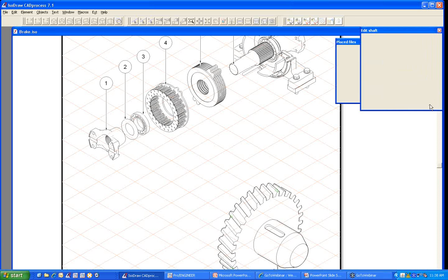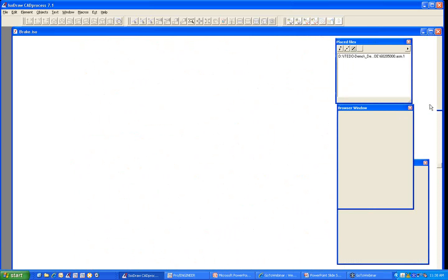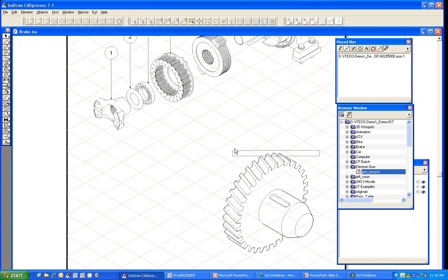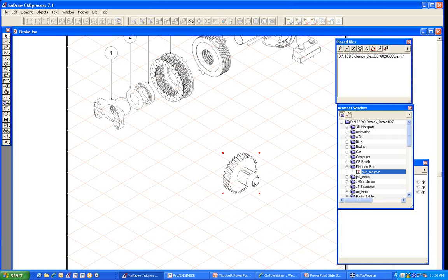And there we go. And of course, as I was drawing that, I was applying the thick thin line style automatically with IsoDraw. So pretty valuable how it does that. Hang on here a second. There we go. So I'll just go ahead and group this, and I'll scale it as might be appropriate for the rest of my drawing, and I bring it up here, and we'll just go over and grab the callout tool real quick and pull a new callout, and it takes on the next sequential number inside of that drawing.